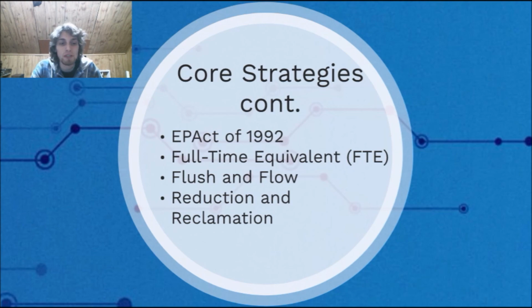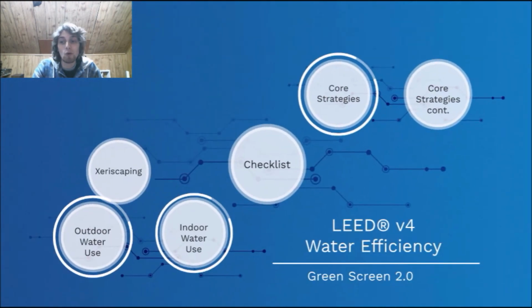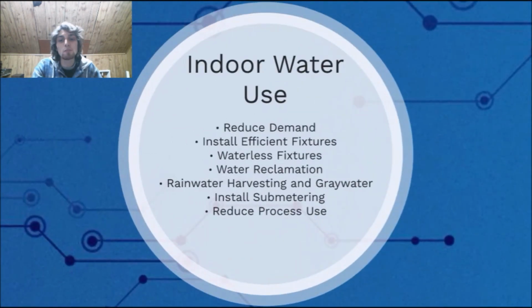Now, there are three types of water use that we're going to find: outdoor, indoor, and process use. You're probably not familiar with process use, which is used for industrial processes, not basic human needs. So not in bathrooms or kitchens, it's used for the industrial processes. So let's head to the indoor water use. So 70% of our daily water is used indoors, and LEED requires a 20% reduction from whatever baseline is set. So once the baseline is set for indoor use, reduce it by 20%.